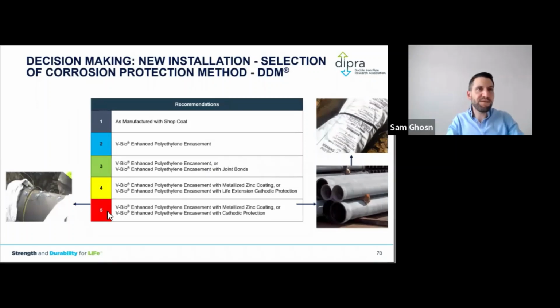They are like 5%, if not less, of the installations we put today, unless the city calls for a type 5 recommendation for every new water main. And that's very aggressive and very unnecessary, because it adds cost to a project that is not really needed, because you might be in non-corrosive environments and all what you need is a bag on the pipe.